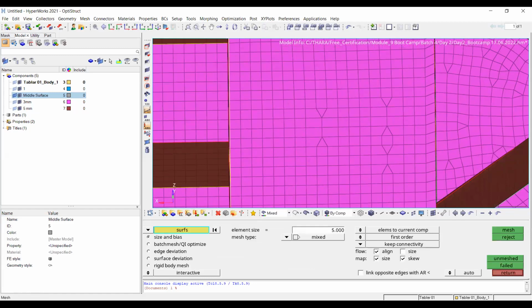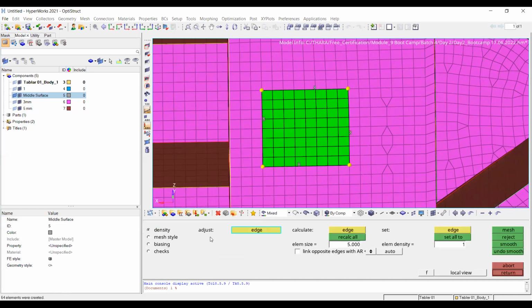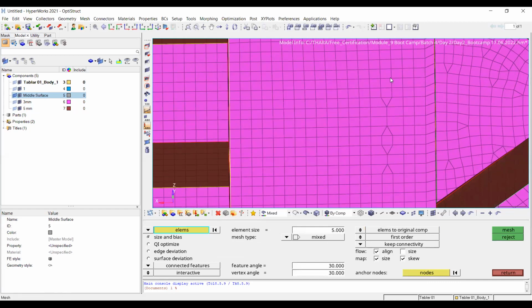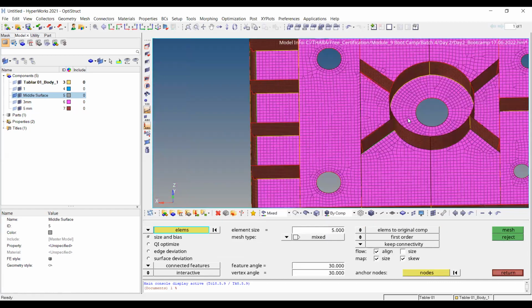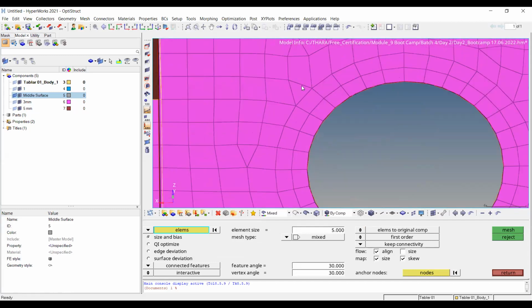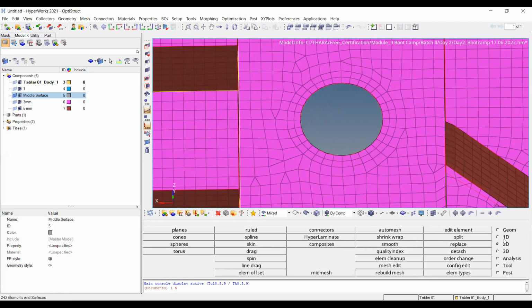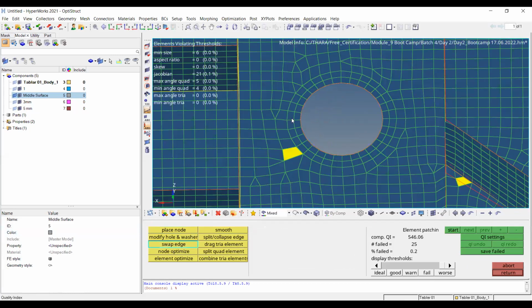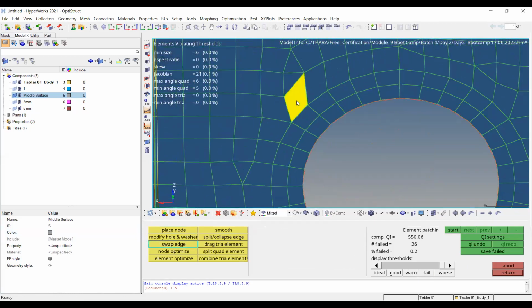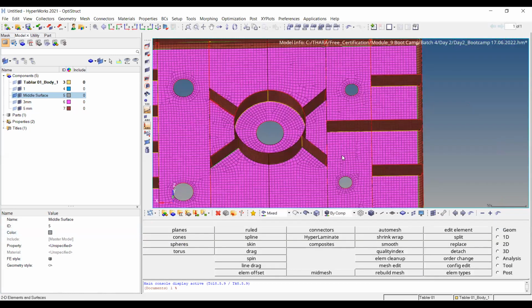How to correct means either you can do the remeshing, or by changing the mesh also, you can correct. This is the recommended mesh which is required. See, now select these elements and mesh this one. See, this is the recommended thing. And see, here the tria which I have kept now, this is not the wrong representation. I need to change the orientation of this tria like this. I need to create it.